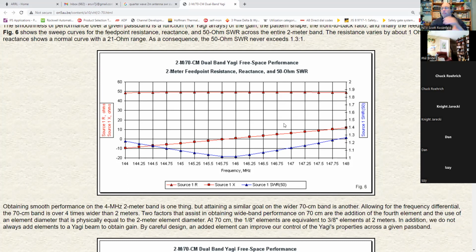Now, and this is something that we haven't discussed yet, it is possible to have a single piece of wire and have two feed points that are separated a distance apart, so that you're able to use a solid, single piece of wire and feed it using something called a gamma match. And that relies on the fact that the feed point is spaced away from the center.